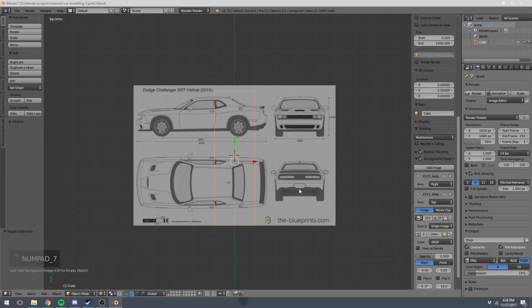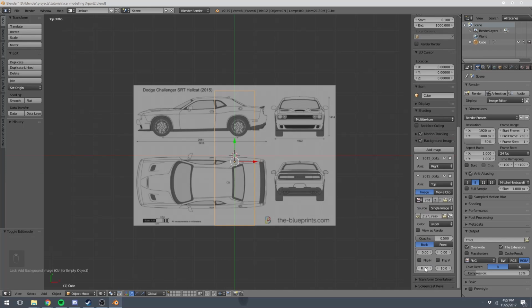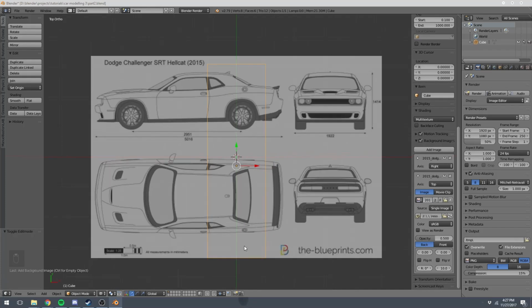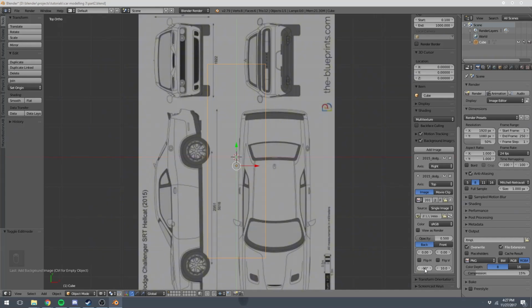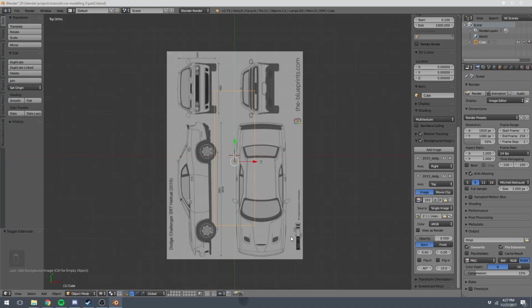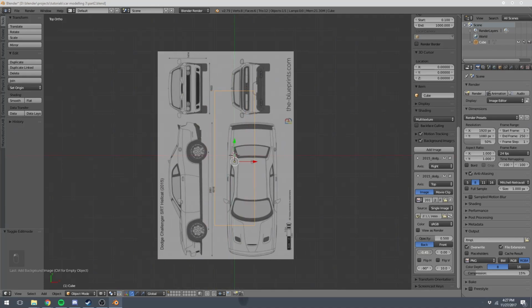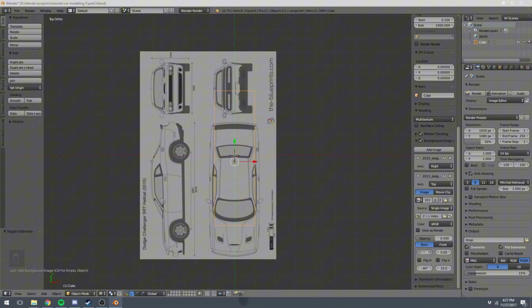And it's not really aligned properly, so we're going to, again, go to this bottom little box here and use these different values to set this up correctly. This R value stands for rotate, so we're just going to type in -90 to get a precise rotation for that, and then just again use these sliders to line it up.